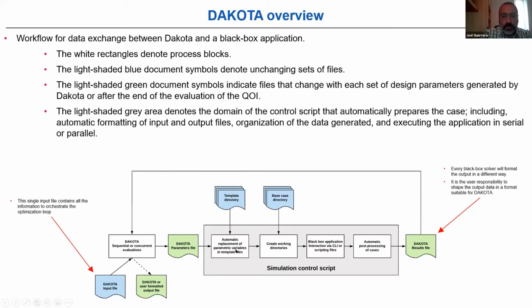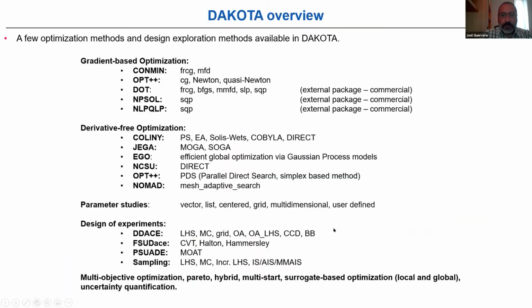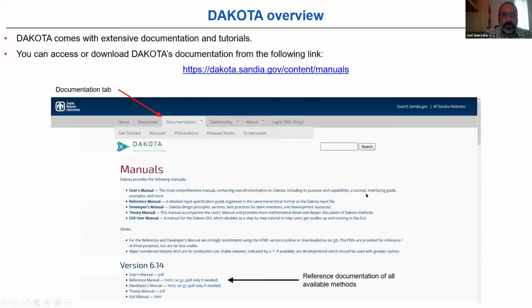Here what you do is just give the sequential steps of what you want to do. Usually in OpenFOAM you go blockMesh, snappyHexMesh, icoFoam, and post processing. So you put your steps and everything here. This is what is happening. Get your output and keep looping. That is how it works. So that is a little bit about documentation.